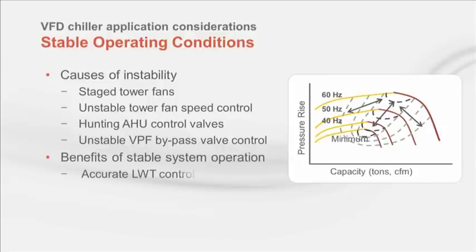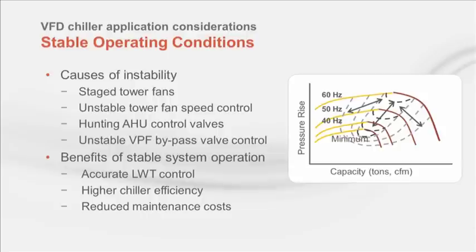Today's variable speed chiller controls are quite responsive. They will quickly make corrections to the chiller operation with changing system conditions. They are also quite smart. If the system is operating with constantly changing conditions, such that a chiller might be pushed outside its safe operating envelope, it will widen its operating margins. This protects the chiller, but reduces its operating efficiency and control accuracy. Exactly how reactive the controls are and how fast they recover and restore efficiency varies by manufacturer.